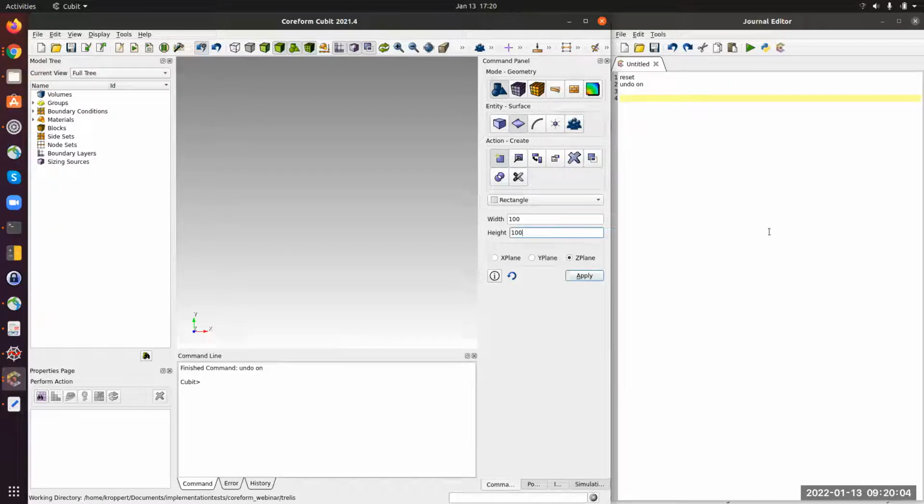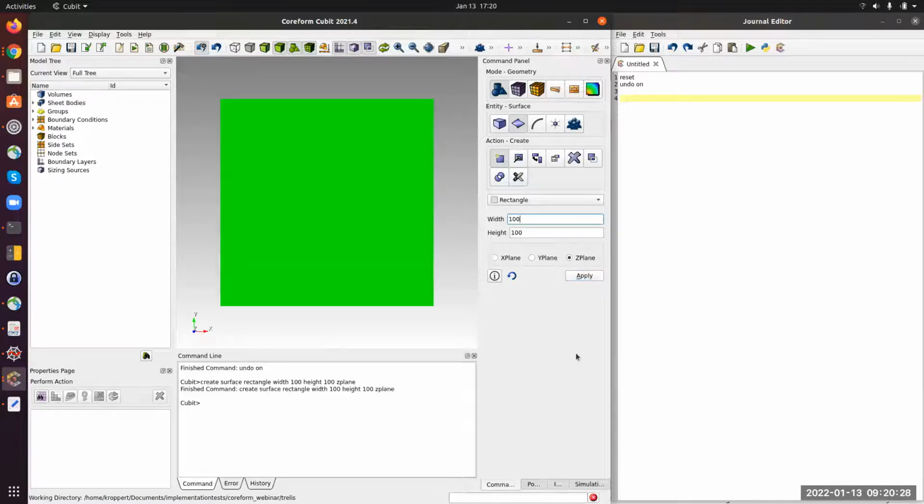Basically, everything here is in SI consistent units, so it would be in meters now. However, I scale it down before exporting the mesh by a factor of 1/1000 to have it consistent with our simulation software, to have everything in meters. Okay, let's click apply. And this is our air domain.